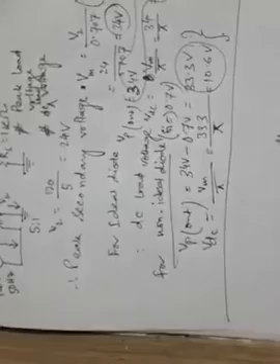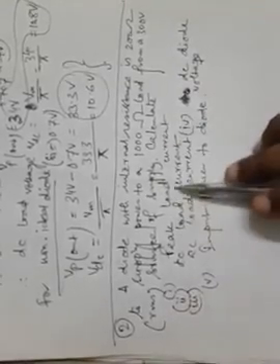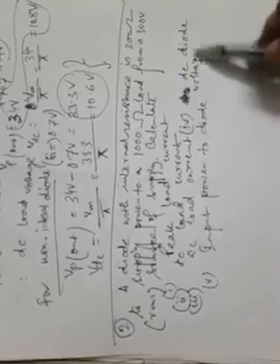So this is the first simple example of solving a problem on half wave rectifier. Now let us look at the second problem. This problem says a diode with internal resistance of 200 ohm is to supply power to a 1000 ohm load from a 300 volt RMS source of supply. You have to calculate peak load current, DC load current, AC load current, DC diode voltage and input power to the diode. So let us look at how this problem can be solved.